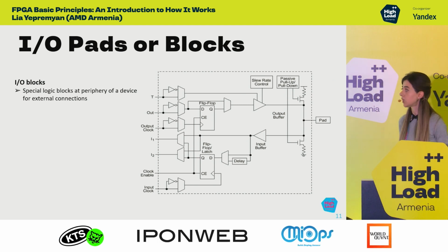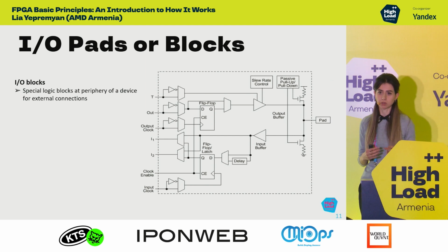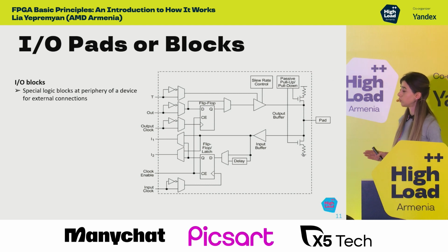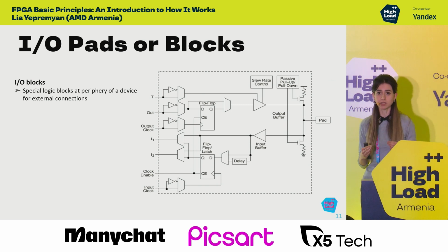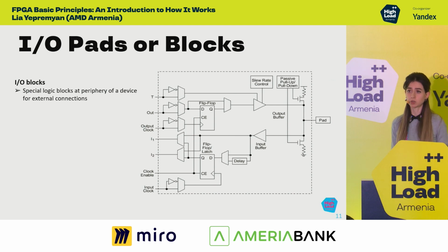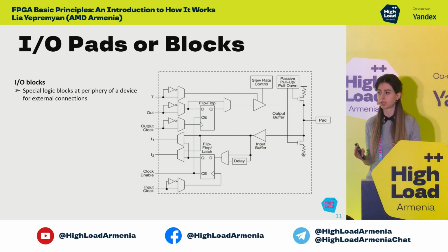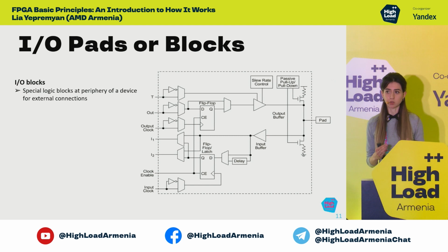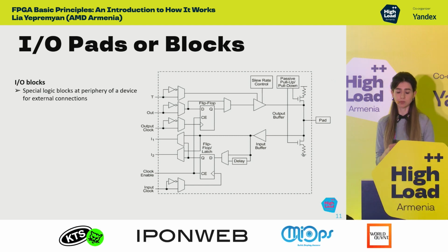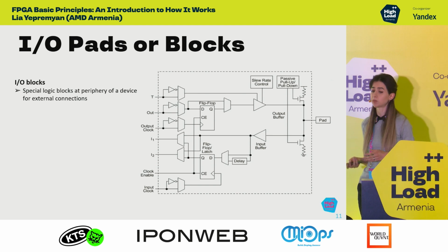Their implementation is very challenging because, unlike lookup tables that can implement a certain logic, input-output cells can supply only one standard, which is chosen by the designer. If our FPGA supported more standards, it would increase the required area used for I/O cells. Also, it would increase the capacitance between pins, which would limit performance.